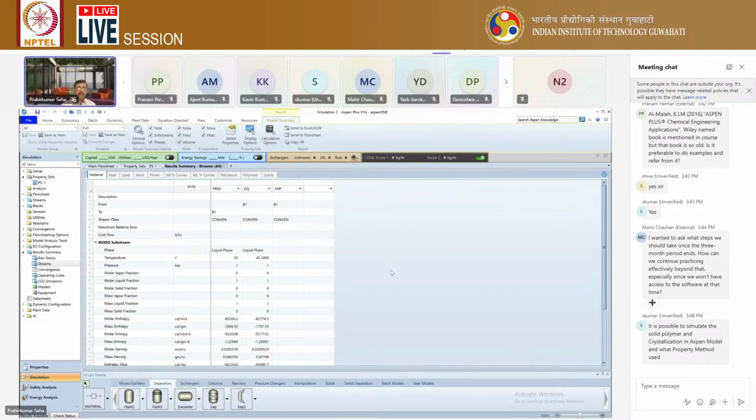And at the end, you will find them, PS1, DSMX, and CPMX. You just click both of them. Okay, so these are the things that you want to include in your property database or display option. And you can put OK. The moment you put it OK, the new two things will come over here. PS1, entropy departure, and heat capacity mixture. Press OK.